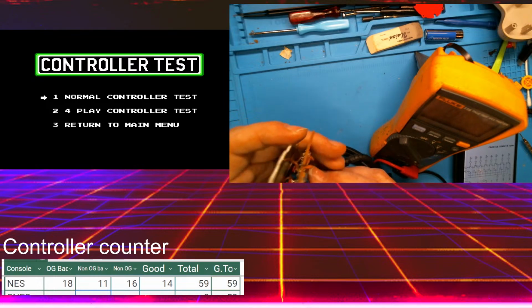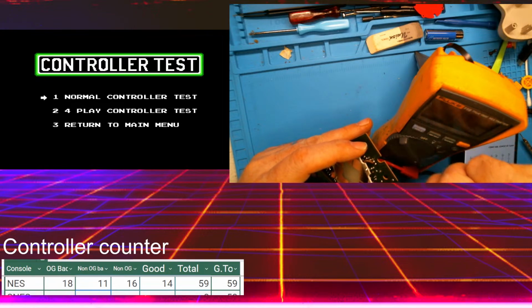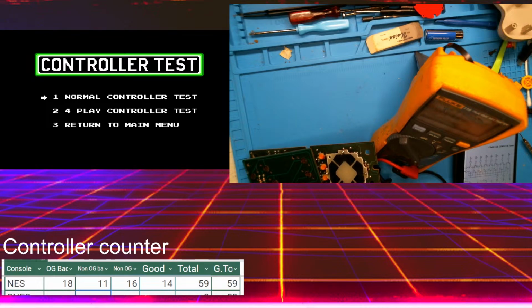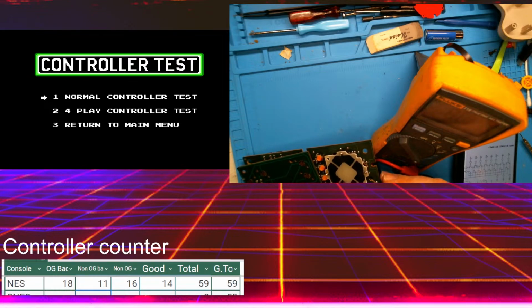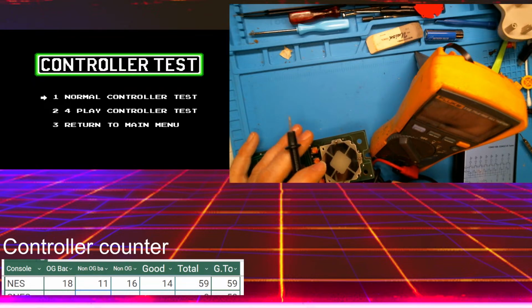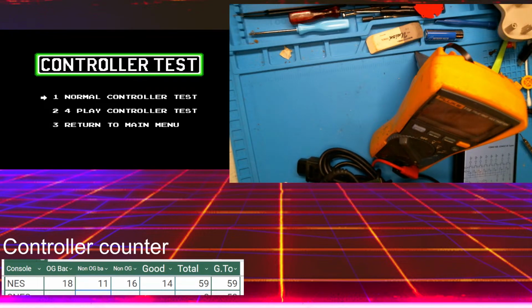And there's a pad over here broken too. I don't know, there's like two pads that are broken. I bet that's killing our continuity. We'll just leave it in diode mode and it will yell at us if it shorts. See? Alright, so this connection should be here. It is not. So they took that.